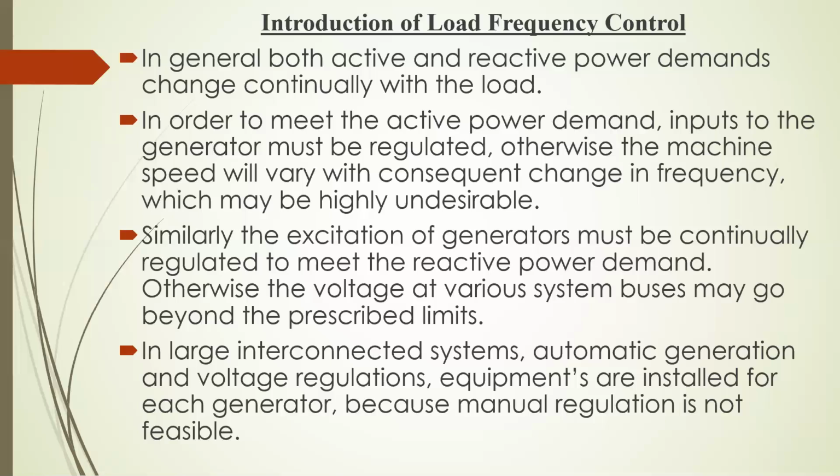The excitation of generators should also be regulated to meet the reactive power demand also. Basically, active power demand changes the frequency and reactive power demand changes the voltage. So to control these two things, active power and reactive power, I need to control the frequency and I need to control the voltage. To control the active power, I need to control the frequency. To control the reactive power, I need to control the change in voltage. If we control these two things, I would be able to control the total power system.